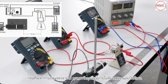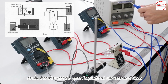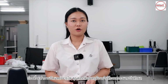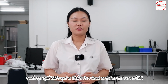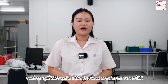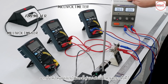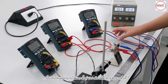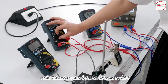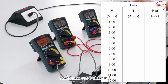Before turning on the power supply, you should measure the temperature in the laboratory and record the value. The measured temperature will then be used to compare the resistance value with the table provided. Next, turn on the power supply and set the voltage according to the table provided. Then, record the current I in ampere.